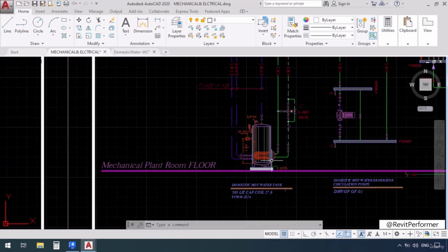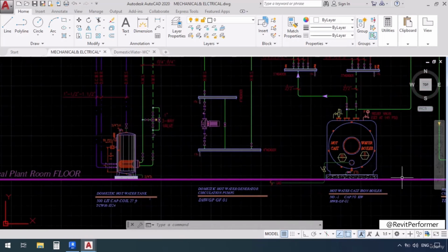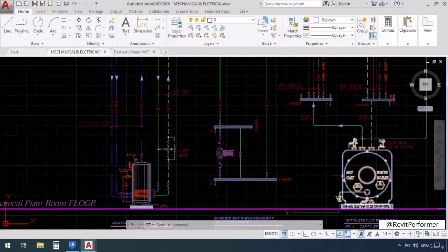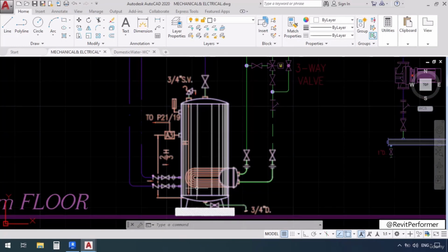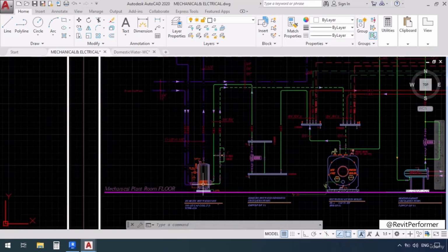the generator. On the other side, where we can find the boiler, we have some water entries. If you take a look right here, you will notice that if we start from the boiler and follow this green line, it's going to continue this way and then goes along in this direction and eventually enters the generator. After that, when that water enters the fan coils, it's going to get out of the generator and come this way and returns back to the boiler.